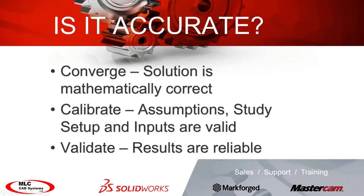Awesome. But the question is, is it accurate? Is that right? Those were the default settings out of the box. I threw it together, ran it, got an answer, and now the hard part comes. I have to figure out whether it's accurate. So I'm going to take you through three major steps that everybody should follow when you're using computer software like this to make sure it's accurate. First thing we're going to do is converge it, then we're going to calibrate it, and then we're going to validate it.